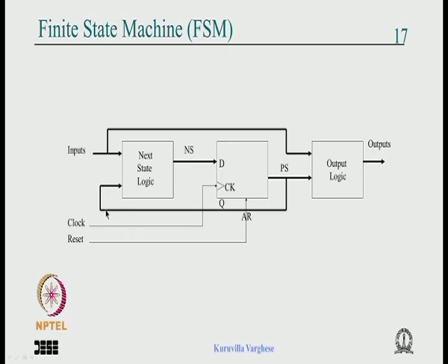If you are familiar with the Karnaugh map, you try to group the minterms. So our question is whether, if you do the assignment in a particular way, you can group it such that the redundancy is removed and this becomes minimal.